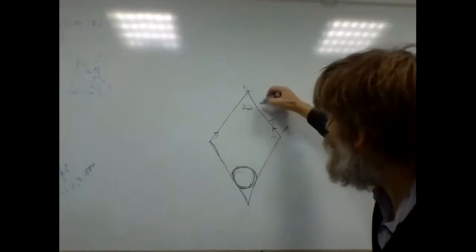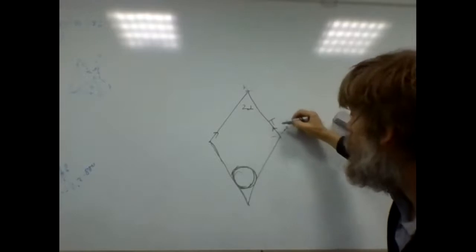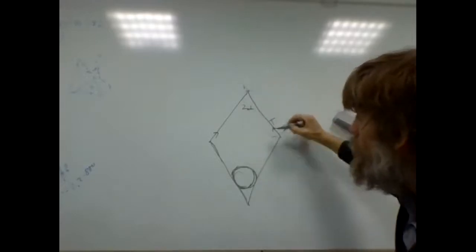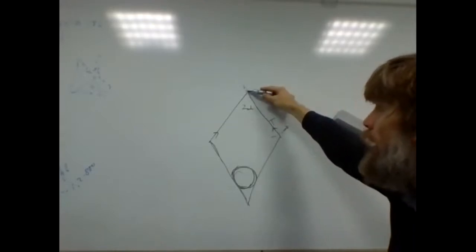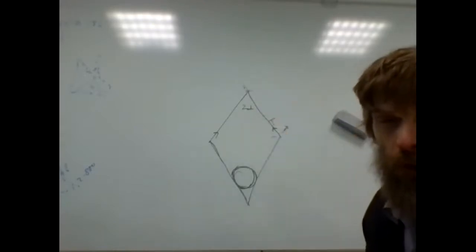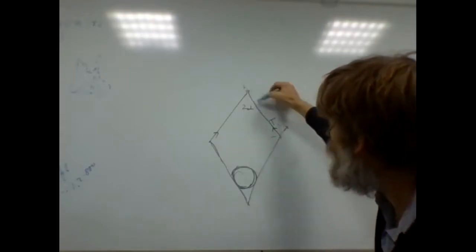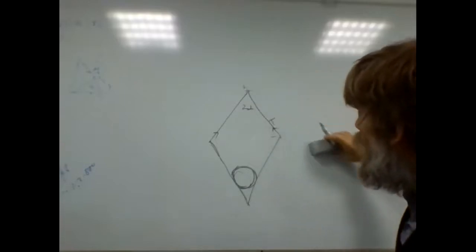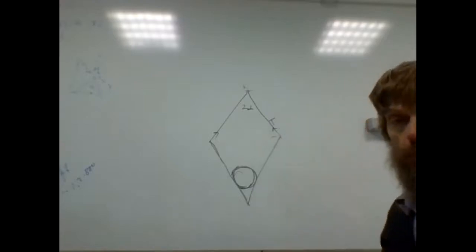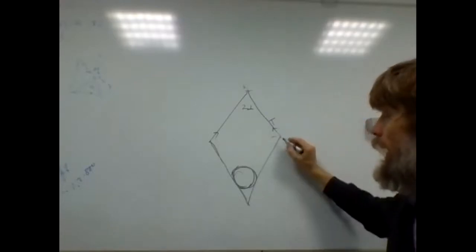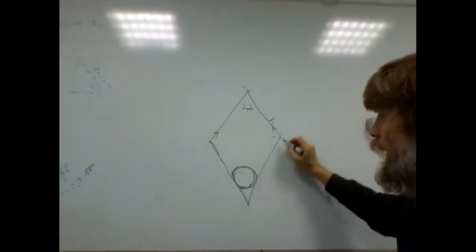Now, if you consider torque acting on this rod relative to this point here, then it is obvious that with only one force T applied, the arm must be 0. So this force T must be applied along the rod. Otherwise, if it were not applied along the rod, we would have torque here, which is not good. So the tension force in this rod must be along the rod. But for this rod, this is not the case, because here we have 3 forces, one here, and one here.